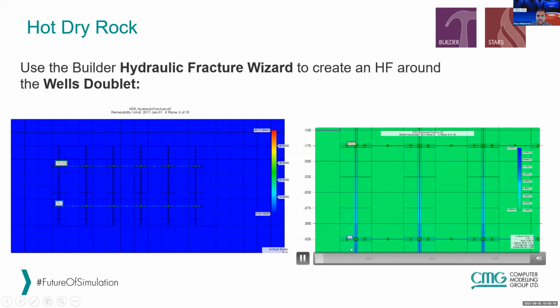On the GEM side, we look at a fully compositional equation of state simulator, which has mainly all the features that we have in STARS, but definitely the main difference would be how the PVT would be handled. GEM would use the equation of state, but STARS would use the K-value table.